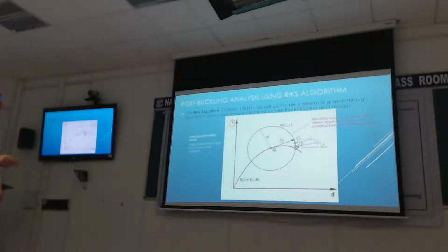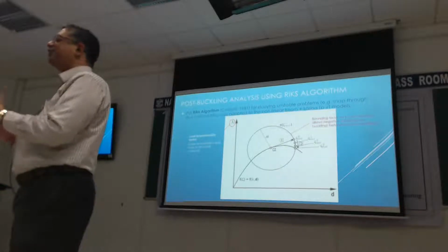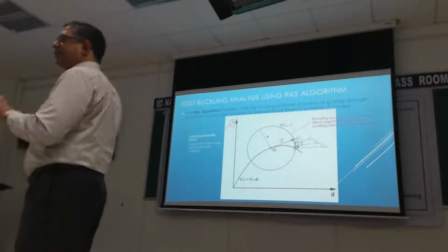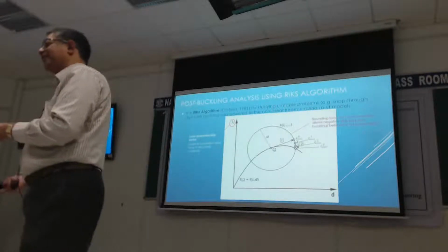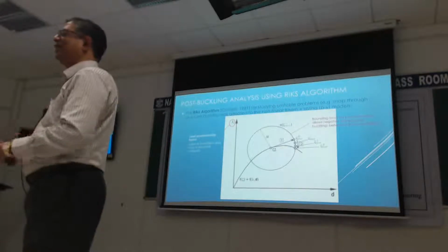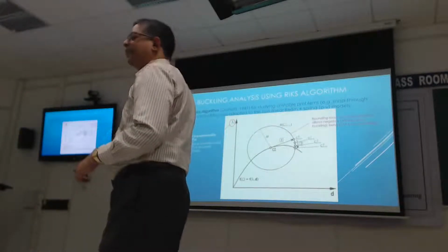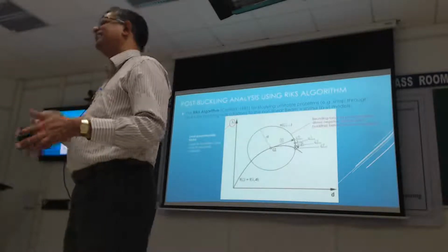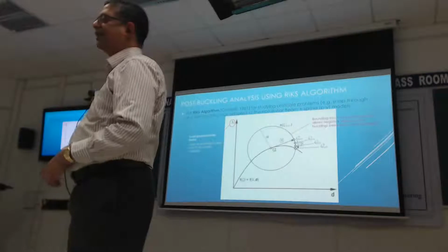This you can choose. You choose the diameter of this, which is given by this delta L parameter. What you will find is if I choose a very large delta L, I'll take very long to converge. I need many steps. Whereas if I choose too small, it will converge for that step, but it will quickly crash trying to go to the next step. So you choose that until it takes 5 or 6 iterations to come back to this. No more than that. And the way they implement it in Abaqus is quite automatic. Once it has learned the stability of your system, it knows the unbalanced forces, so it will allow you to choose a delta L which is reasonable.